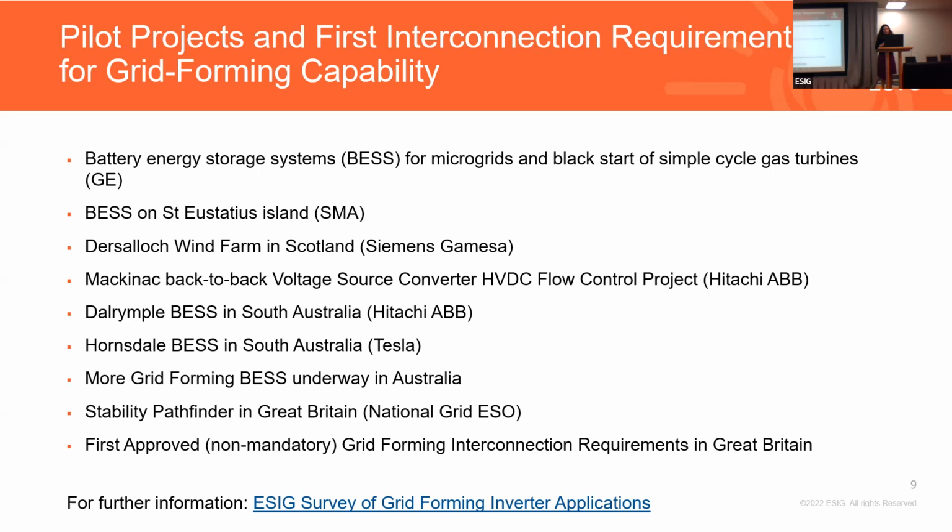Hornsdale battery storage project in South Australia. It's a 150 megawatt battery storage project. Initially it was built as grid following, but currently is undergoing conversion of inverters to grid forming mode. And Deepak also had the slide during the tutorial. During this conversion exercise, a coal-fired plant tripped offline nearby, and they were able to record the difference between how the entire plant responded to that generator trip, which looks like a primary frequency response, similar to how a synchronous generator would have responded. But if you look at just those inverters that were already in grid forming mode, you can see a response that's similar to the inertial response of a synchronous generator, because the control mode that they implemented there is virtual synchronous machine mode.